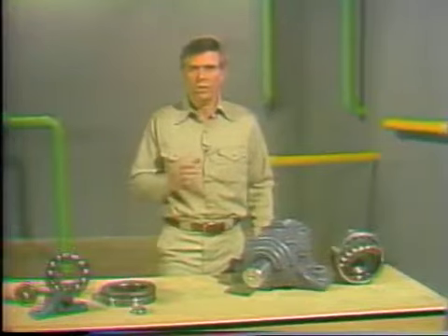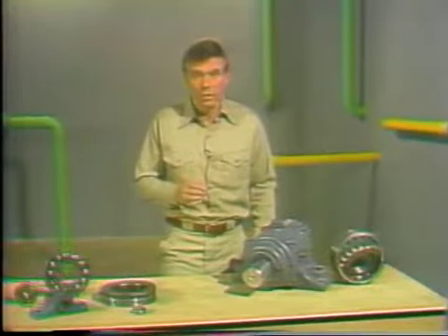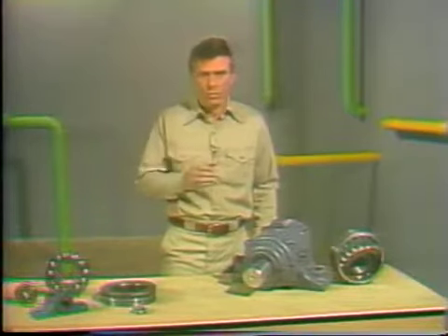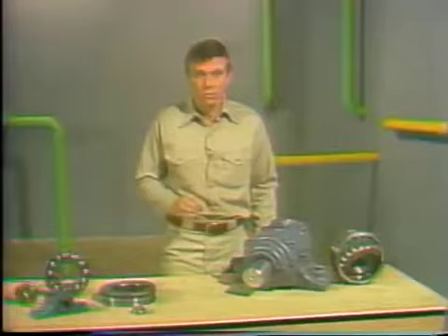Friction is the resistance to motion that exists between two bodies in contact with each other. In order to move one or both of these bodies, friction must be reduced. The majority of bearings fit into one of two categories: sliding surface bearings and rolling contact bearings. With sliding surface bearings, two surfaces with a lubricant between them slide over each other. With rolling contact bearings, one surface rolls over another surface with lubricant in between.